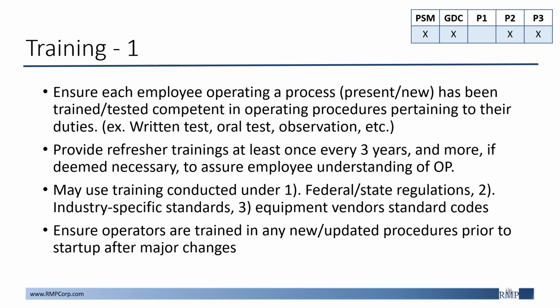Also, not making sure that all documentation of each person's training is kept and filed, and that it shows how understanding of the training was verified. This could simply be a copy of the test they took. And lastly, having an operating procedure training that is not facility specific. Always make sure that your operating procedure training is facility specific.